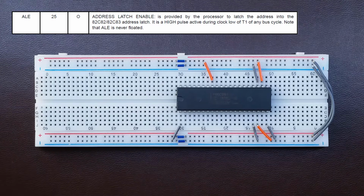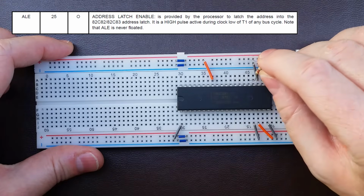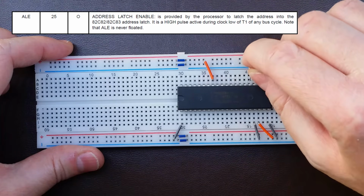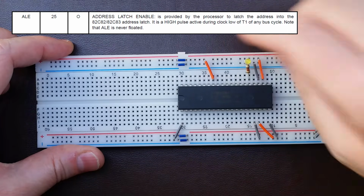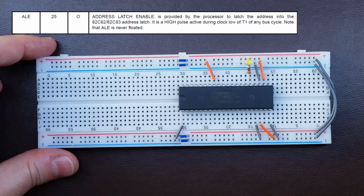This signal lets us tell them apart. That's why I'm going to put my LED between that signal, which is pin 25, and the ground. I've got those LEDs already soldered with some current limiting resistors, so we can simply hook them up.